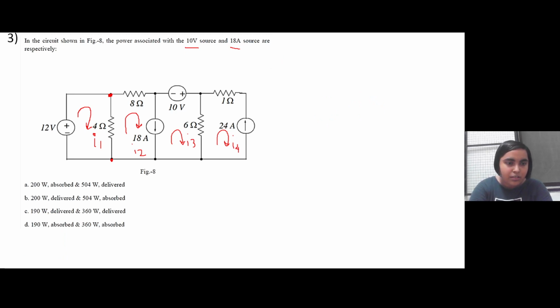Okay, now let's apply equations in each of the KVL in each of the loops. So for the first, let's assume this is loop 1. First we can simplify this problem even further. Look at this particular branch. 18 ampere current is flowing in this direction, it is given in the question. From our assumption, I2 is flowing from A to O, whereas I3 is flowing from O to A. So basically I3 is in the reverse direction.